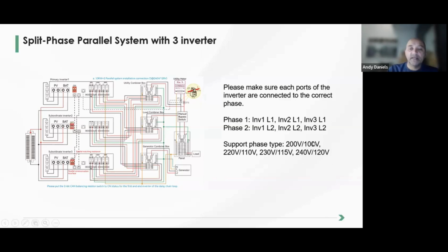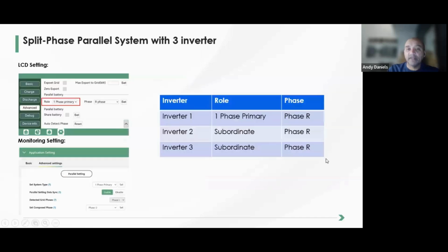Okay, so this here is obviously for your output in off-grid mode. Remember that you obviously have to set this correctly, but the voltage that comes through when the grid is on will always be grid following. Always whatever the grid voltage is, that is what it'll be. Here we have a split phase parallel system with 3 inverters.